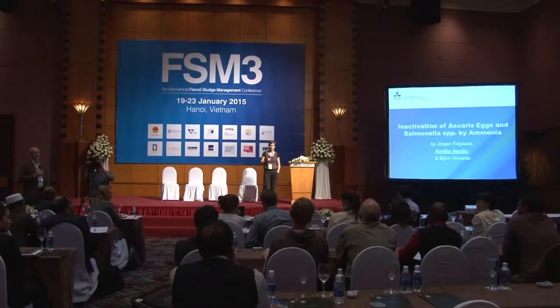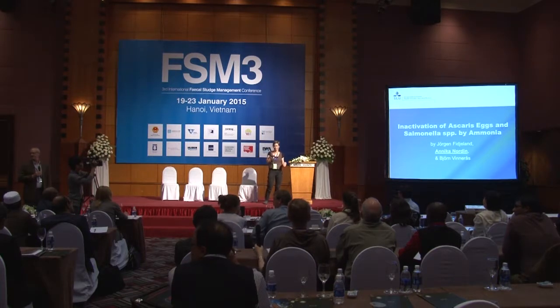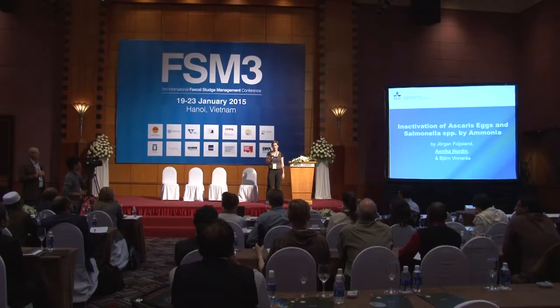Any other questions for Annika? Yes. You did a study of 50 days. Did you notice that there might be any adaptation of bacteria getting used to these concentrations and then in fact become resistant against your disinfectant? It has been observed for enterococci that they tend to adapt. And also if you study enterococci that are naturally present in septic systems and urine tanks, they seem to tolerate ammonia better.